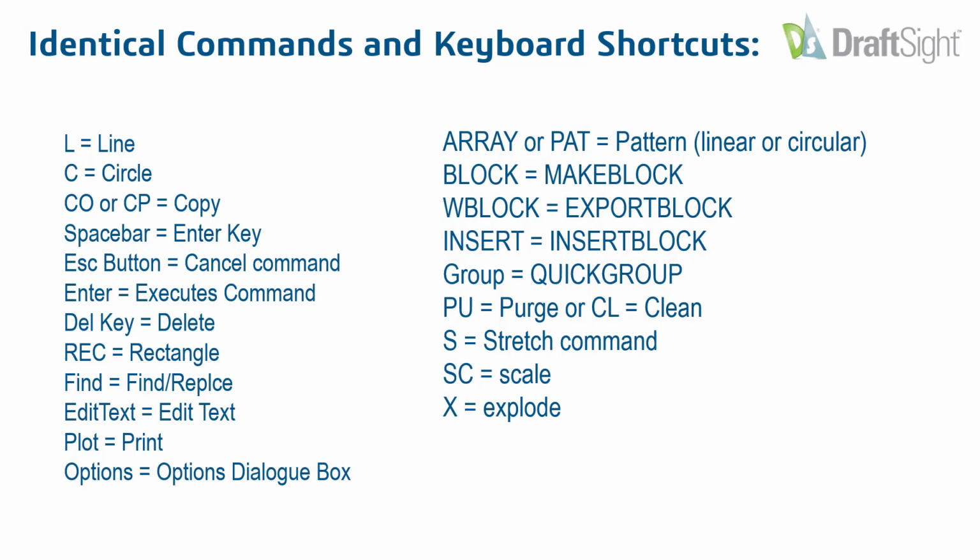Oh, okay, yeah, that's what that is. You can go back to these later as well. You also have REC for rectangle, or you can type it all out. It has a filter command that filters as much as you type, and you can select that as well. Also S for stretch and SC for scale, and of course X for explode.